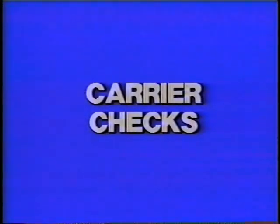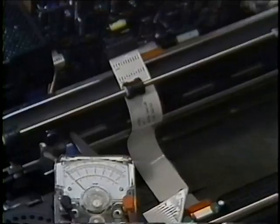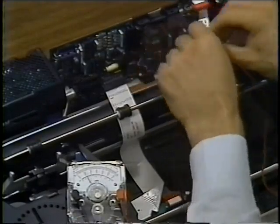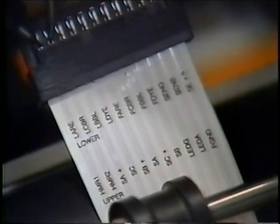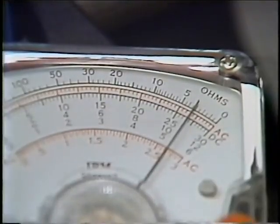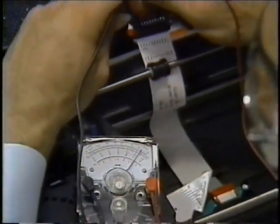This section covers checks of some of the parts in the carrier. To check the hammer solenoid, you must perform a resistance check of the solenoid. You must first zero the meter and check the accuracy of the meter on resistor R603. Remember to turn power off. When you are sure your meter is good, measure the hammer solenoid resistance from pin 1 to pin 2 on the carrier cable connector J4P. The hammer solenoid must read from 2 to 4 ohms. Any reading higher than 4 ohms or lower than 2 ohms is bad.